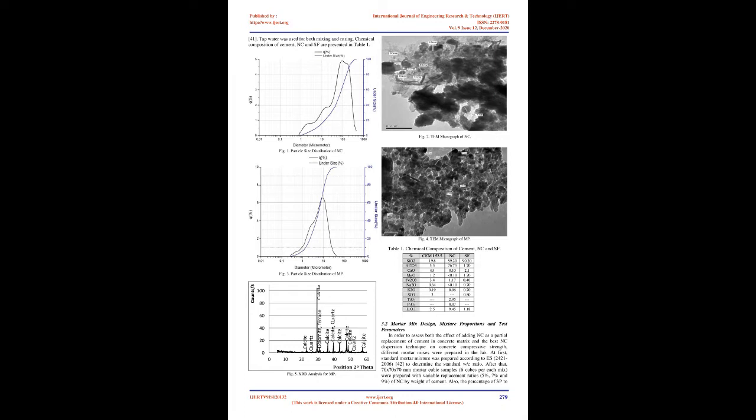Ahmed et al. 31 reported that the addition of NC as cement replacement increased the viscosity of self-consolidating concrete, SCC, which prevented the segregation and bleeding of fresh mixture. NC improved mechanical properties of SCC especially at early ages in addition to increasing its durability. The ratios of NC were 1%, 2%, and 3% by weight of cement, and the best improvements in test results were observed at 3%.